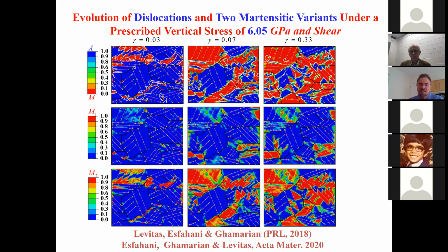And actually, there are many papers where preliminary plastic deformation is used to increase hysteresis, for example, for energy absorption purposes. So if you want to talk about real applications of shape memory alloys, this is not a good method because it actually spoils some of the effects. It increases hysteresis, it increases energy absorption for shape memory alloys.